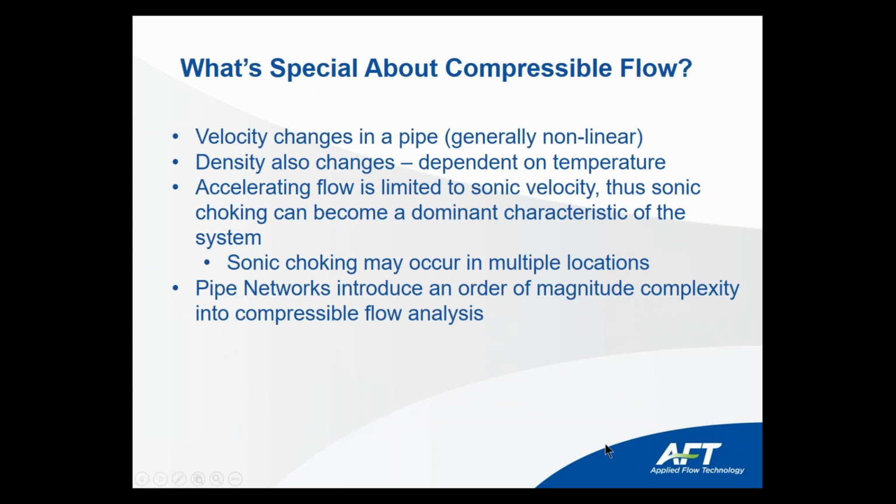So specifically regarding AFT Arrow, which is our steady state compressible solver, what makes compressible flow analysis special? Well, first off, unlike liquid systems, there's a significant velocity change in the piping for gaseous systems. So the density is also changing, and both of those are going to have a strong dependency on temperature. Now, as such, those changes are generally non-linear.